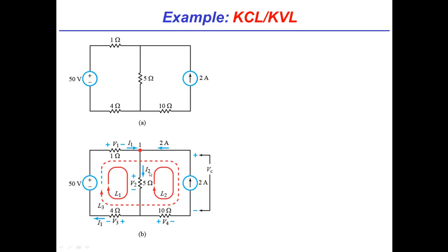All right. So in the bottom circuit, what we've done is really just labeled a number of unknown currents and voltages. And again, arbitrary, the way we've done it. So for example, we've called V1 positive when you drop from this plus to this minus. I could have done it the other way. And I1 is defined as pointing to the right on this, and I2 down. And you can see by continuity that I1 going this way is the same I1 down here going to the left, right? Most of the time people don't bother to label it twice. This is the same current.